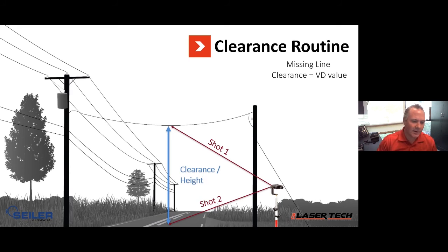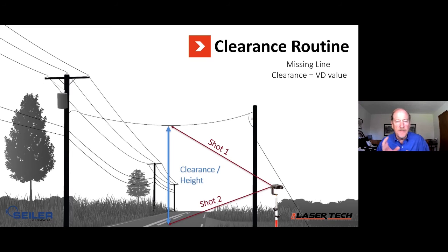It will continuously fire the laser and update that horizontal distance, and you can pan back and forth and try to get as close as you can to that 45 feet again, and then you've got 2 horizontal distances that are the same for shot 1, shot 2. Right, that's a great tip, and it takes a little practice and technique to get it right. And when you release that trigger with your good distance, you want to stay nice and steady there. But that's a great way to try to find those 2 points in space. That one that's kind of unclear on the roadway. Yeah.